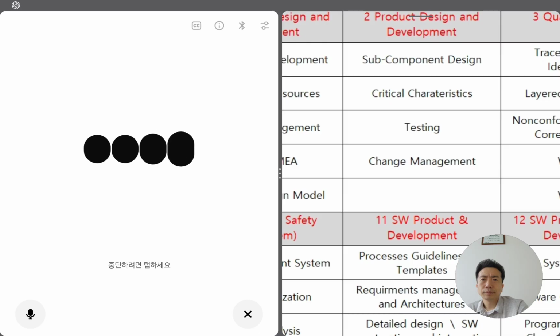2. In-car driver monitoring camera. Infrared LED performance for night and low light. If the LED fails, the DMS system won't detect the driver properly. Eye tracking accuracy and calibration are safety critical for driver monitoring. Temperature resistance: high cabin heat, must function at plus 85 degrees Celsius or higher. Mechanical robustness, mounting bracket: the camera must stay fixed, no vibration or movement. ESD and EOS protection prevents damage from electrical surges inside the vehicle.